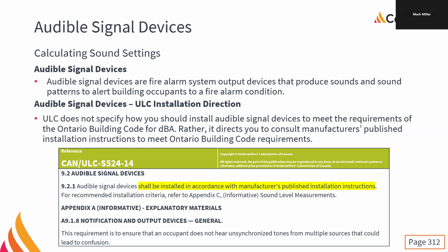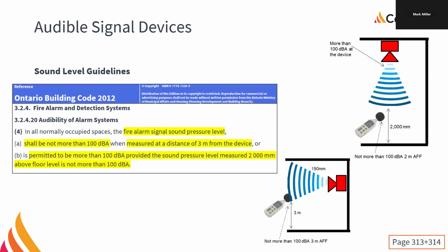Because we have to check the decibel rating. We can't just go, yeah, that sounds good. We have to actually measure it. And you can't use your phone for this. Yes, we've got sound meter apps on the phones. They are not calibrated. They're surprisingly accurate, but they're not officially correct. So we have to use an actual sound pressure meter. This is part of what's done during verification.